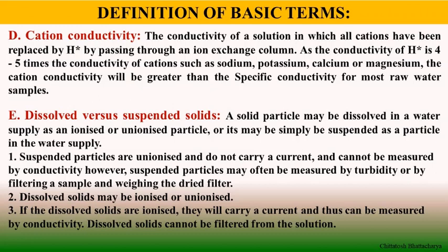Now, to understand total dissolved solids or suspended solids, the solid particle may be dissolved in a water supply in an ionized or unionized form, or it may simply be suspended as a particle in the water supply. Suspended particles are unionized and do not carry a current and cannot be measured by conductivity, but suspended particles may often be measured by another term which is called turbidity, which can be done by filtering a sample and weighing the dried filter.